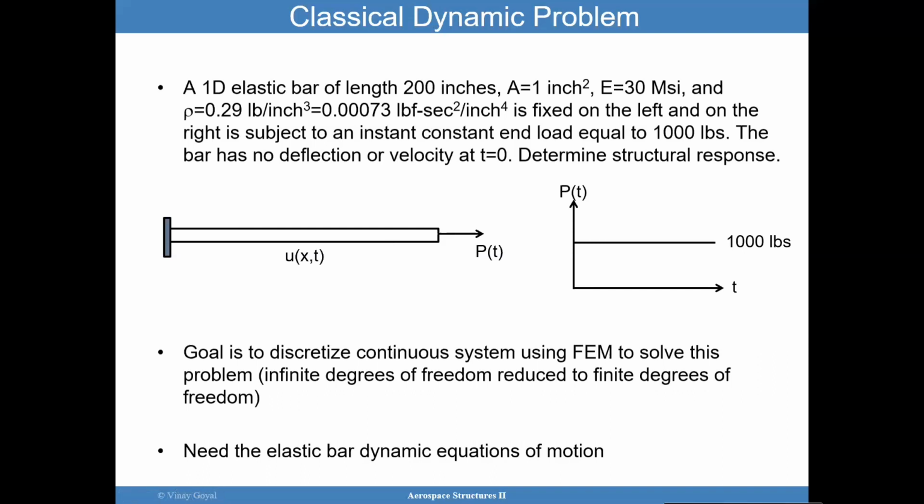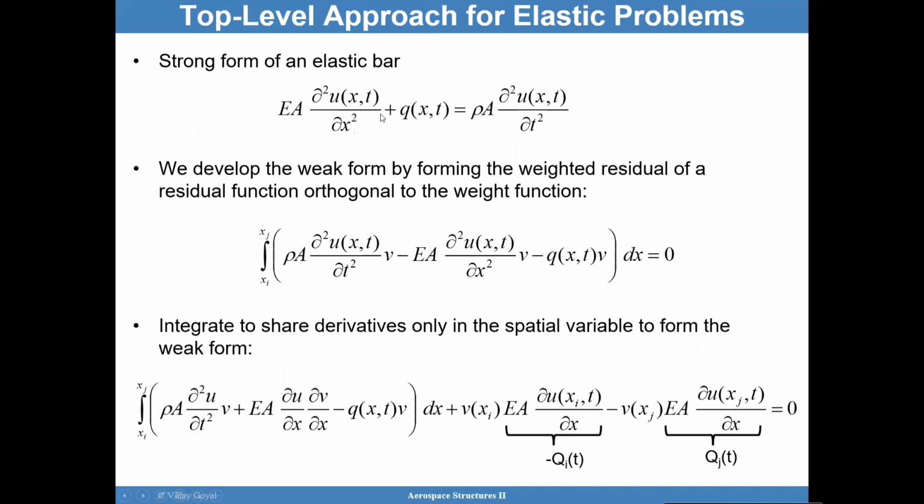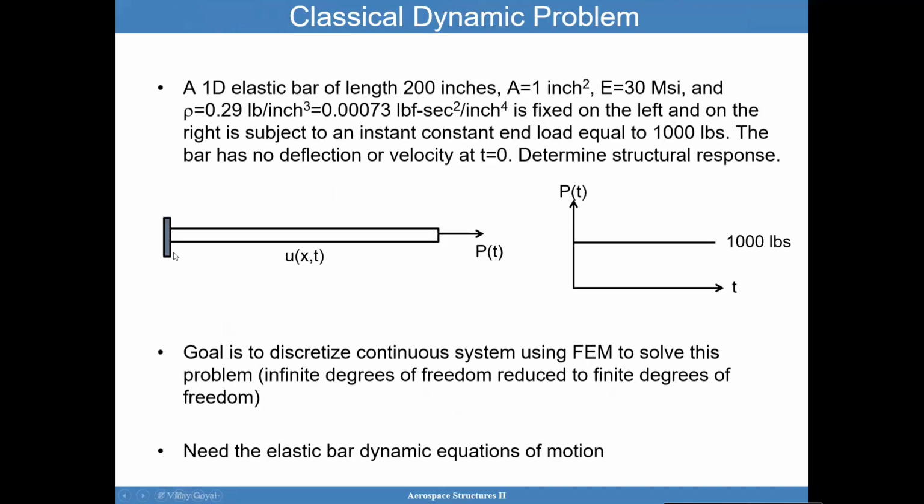So what we want to do is to discretize this continuous system. And so we will then do that now. Here is the differential equation that corresponds to the elastic bar. This is called the strong form of the problem, or the governing equation to the problem, which is a mathematical representation of the behavior of this bar subject to these loading conditions.